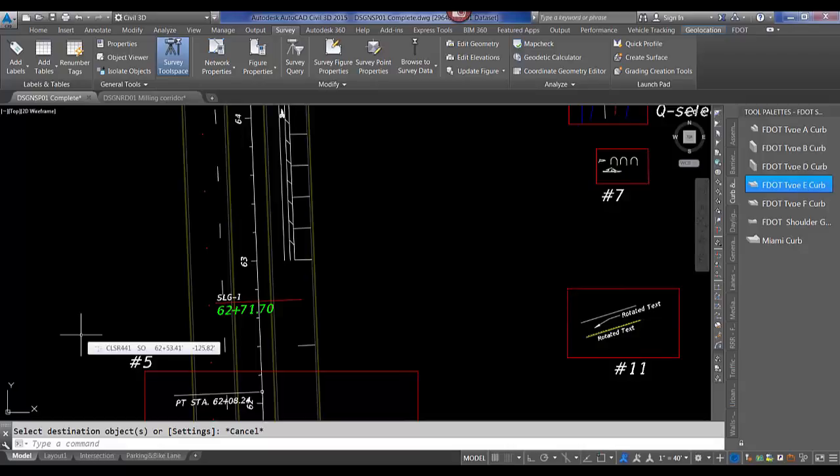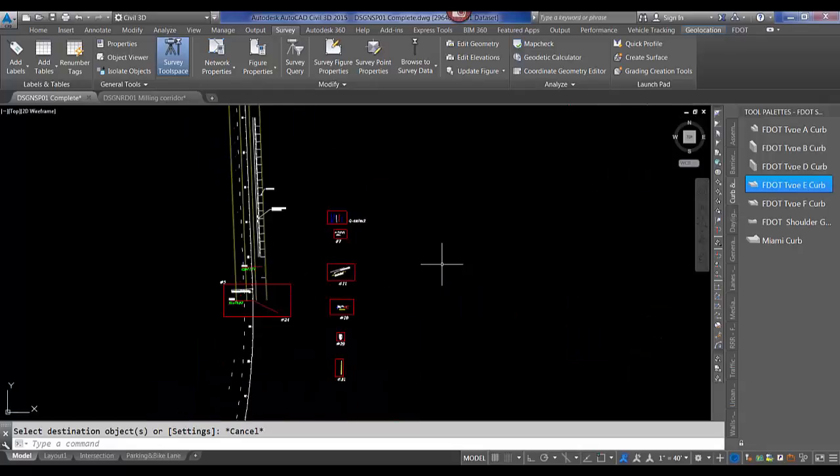Okay, number 18, creating a custom subassembly palette. All right, for those that are actively modeling and using a combination of our FDOT subassemblies and Civil 3D out-of-the-box assemblies, with the number of conditional assemblies that you can string together, it could be a little cumbersome to recreate that on each of your projects.